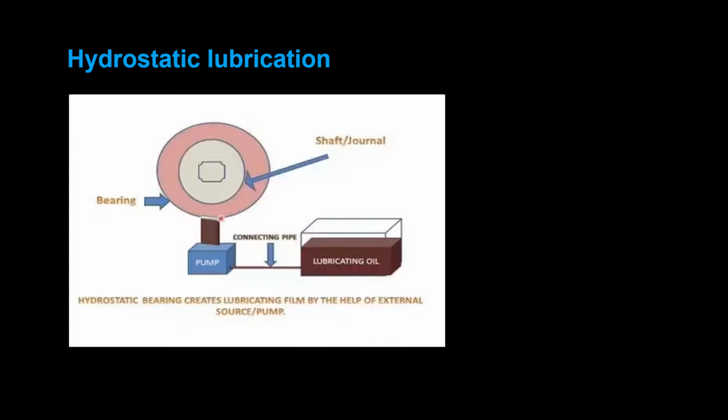So unlike hydrodynamic lubrication, this kind of lubrication does not require motion of one surface relative to another. We shall not deal with hydrostatic lubrication, but the subject should be considered in the designing of bearings where the velocities are small or zero and where the frictional resistance is to be an absolute minimum.